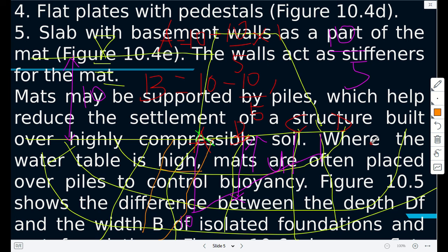And then when you design the dam, you always find the factor of safety against uplift, which is this uplift force divided by the, anyone, which force resists the ability to go up? Factor of safety against uplift.